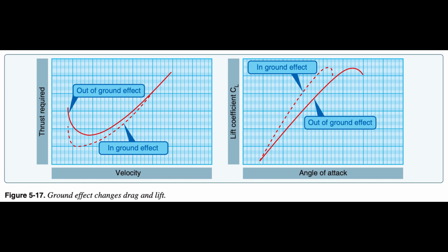It is also important that a definite climb be established before a pilot retracts the landing gear or flaps. Never retract the landing gear or flaps prior to establishing a positive rate of climb and only after achieving a safe altitude. If, during the landing phase of flight, the aircraft is brought into ground effect with a constant AOA, the aircraft experiences an increase in CL and a reduction in the thrust required, and a floating effect may occur.